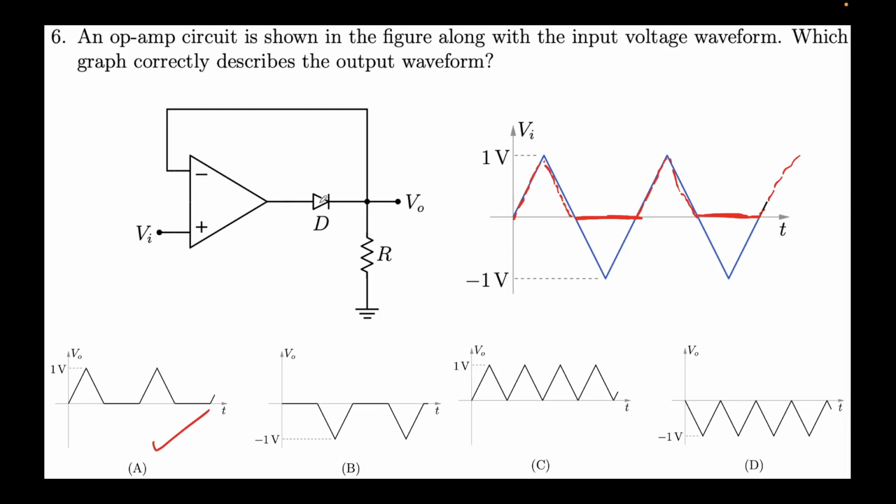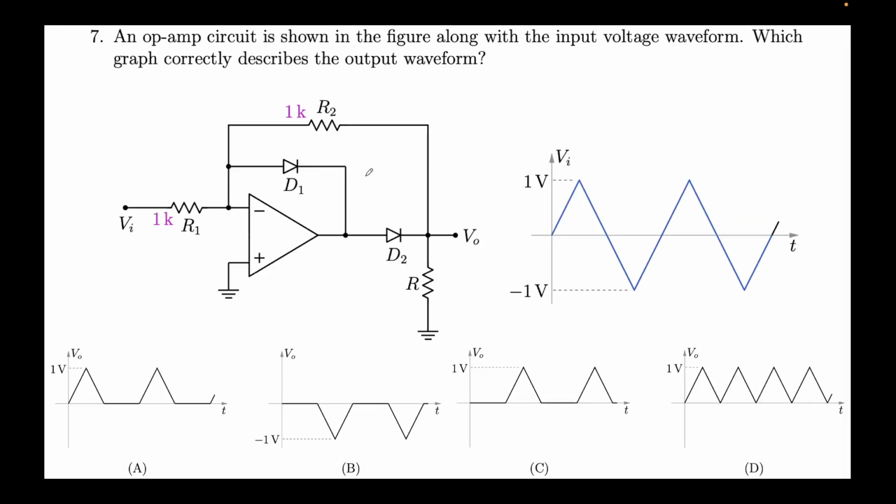You just have to follow whether the diode is on or off, and then split it into two cases, and we try to figure out the value. The rest is very simple op amp, like the virtual short and just the KCL, and we'll be fine.